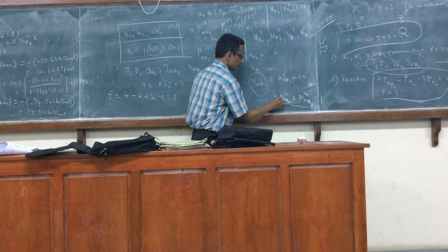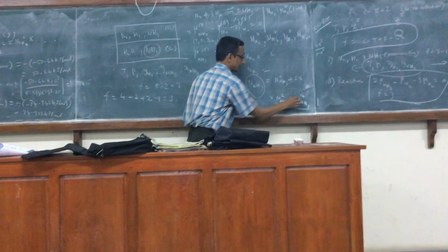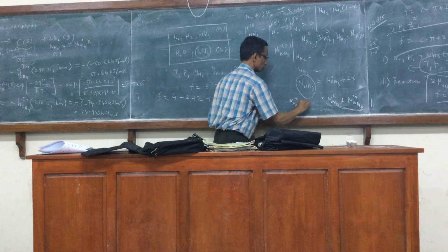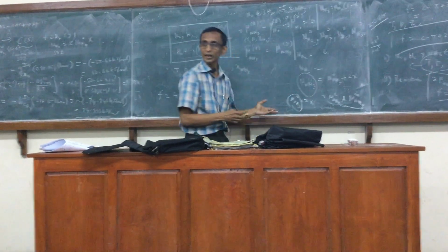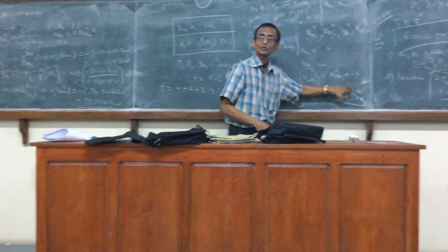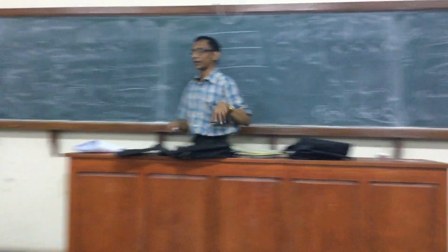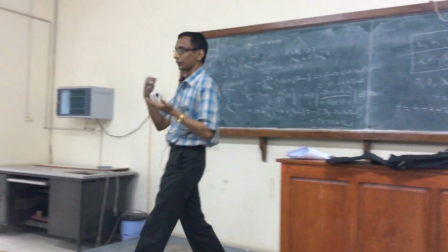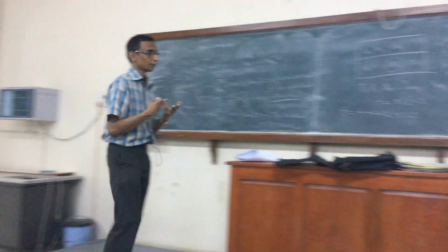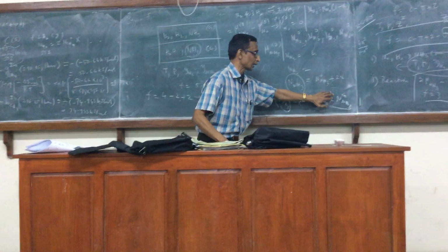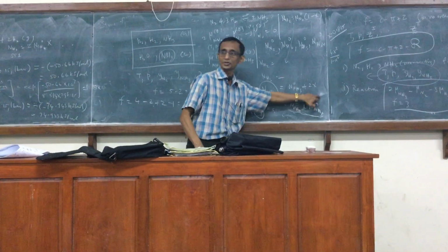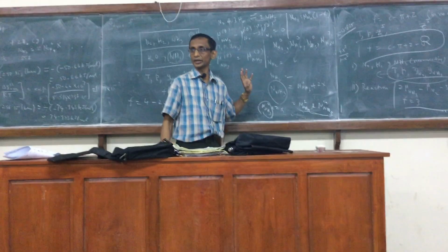This will give an equation connecting the two. Now this we will have to specify. So on top of x, we have to choose one of these as variables. The problem will automatically give rise to two variables that you have to determine, because for the third variable NH3 L, I have this equation: once I know x and NH3 G, I know NH3 L.